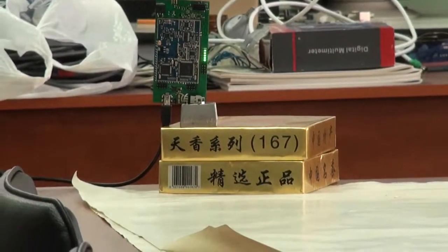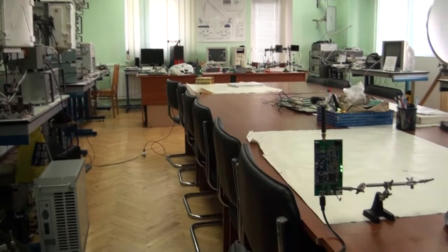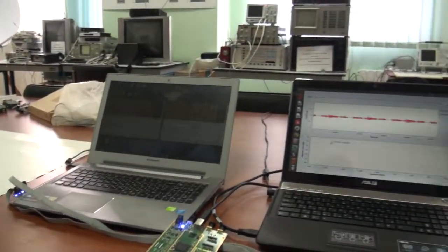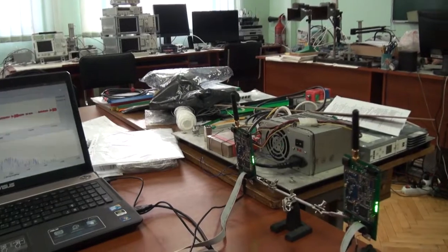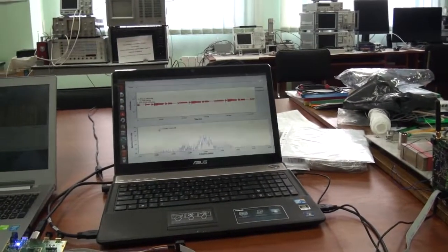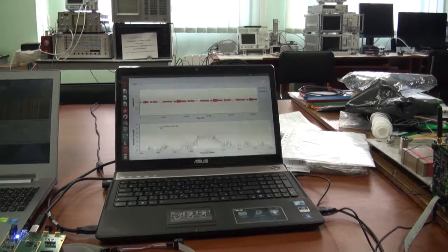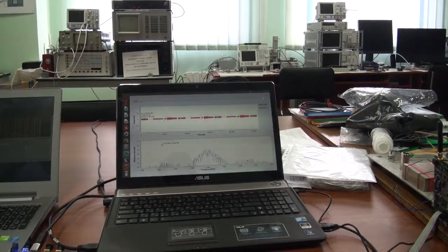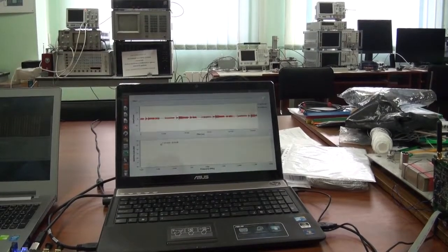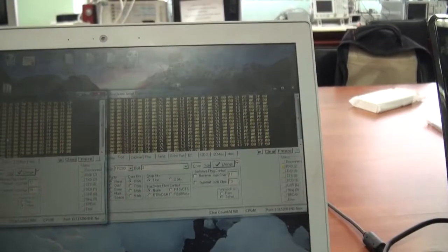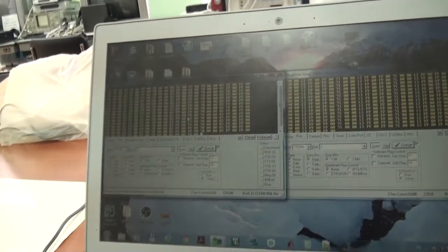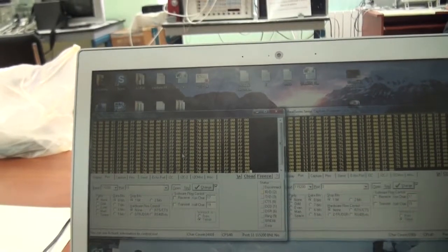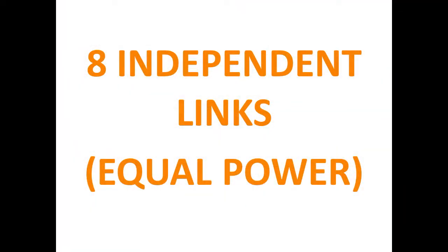Here, the signal from a transmitter with another key of physical layer encryption is recognized as interference, not a signal from another channel, and is suppressed in the receiver. And this is the reason why power equalization is not necessary in this case. So, the signal from a more distant desired transmitter can be received even if there is a closer transmitter with another key. And we can conclude that independent CDMA networks will work in some area without additional arrangements due to their spatial location.